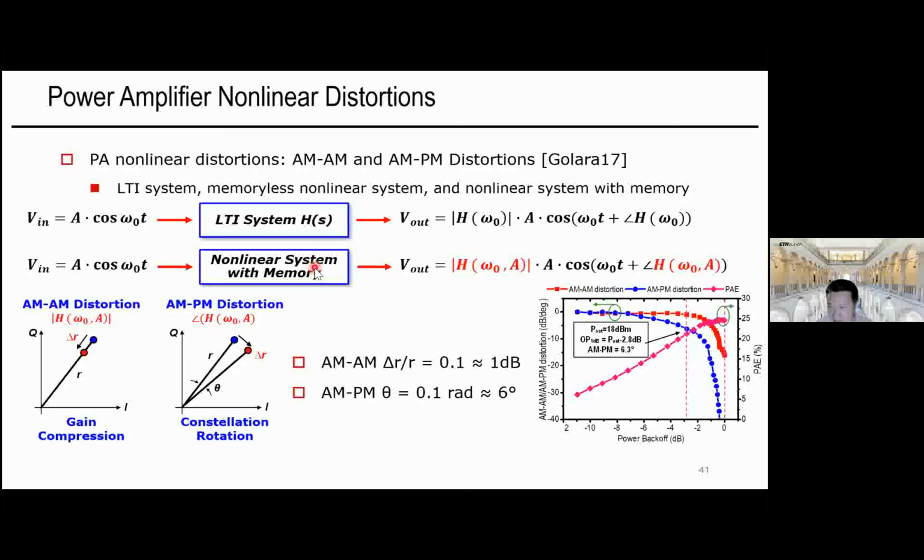The PA is actually a large signal thing. During the large signal driving, its biasing is changing constantly through your driving. Therefore, in many cases, we also need to model the large signal stability of the PA, right? There are different ways to test the PA stability for large signals. I think in practical designs, that's probably even more important than checking the small signal stability. Yeah. Thanks, Professor.